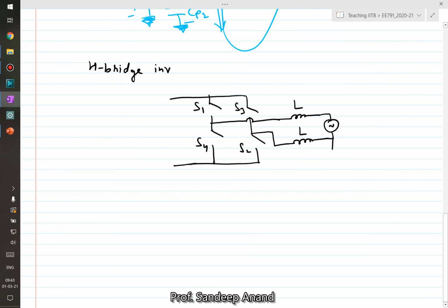Now, as I told you, on the substation, the neutral would be grounded. So this is the neutral, it's grounded. This is phase A. On the DC side, we have panels which are connected, and to avoid the flow of the high frequency differential current, we would usually also connect a DC link capacitor, for 2 reasons.